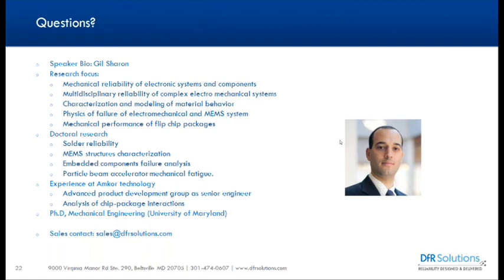Sorry, Gil. Did we answer why avoid conformal coating BGA devices? I'm not saying to avoid conformal coating BGA devices. What I'm saying is that conformal coating is not underfill. Do not try to use conformal coat as underfill. If you do a thin conformal coat like you're supposed to, you saw there's no difference between them.